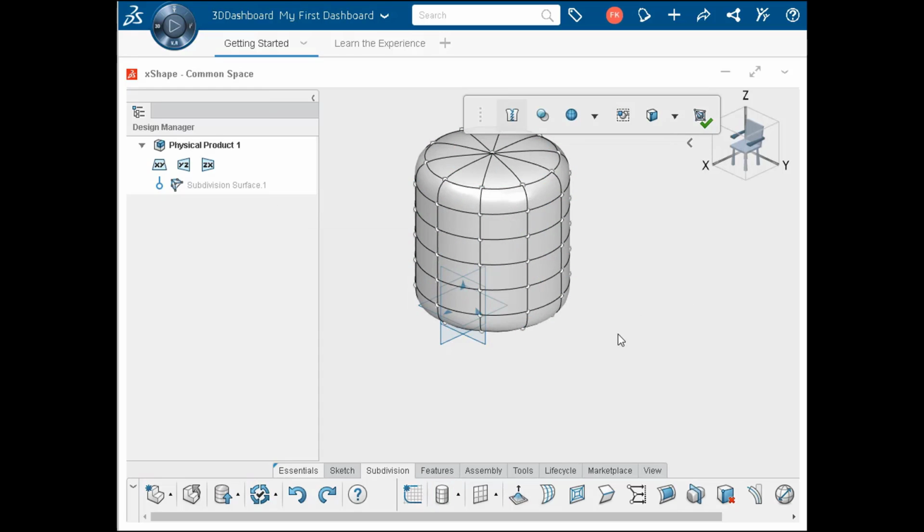We use view orientations to change our perspective on the model, and it can also be useful for making selections, like box selections, easier. The box edges are horizontal and vertical, so sometimes it is easier to change the view orientation to select an angled set of vertices. Some common tools for changing the view orientation are the triad and the triad menu with isometric. But there are many keyboard shortcuts that can also be used to quickly zoom and change the view orientation.